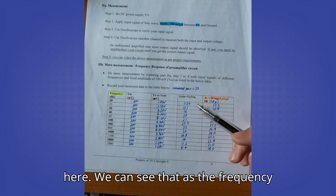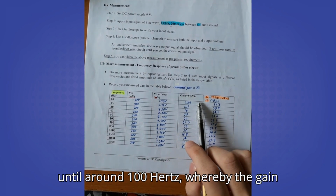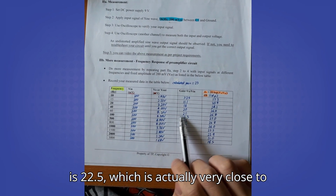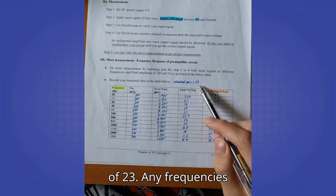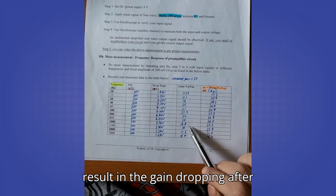We can see that as the frequency increases, the gain also increases until around 100 Hz, whereby the gain is 22.5, which is actually very close to the calculated gain previously mentioned of 23. Any frequencies higher than its cutoff frequency will result in the gain dropping.